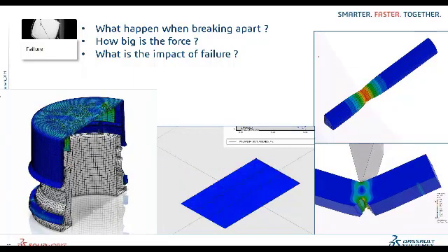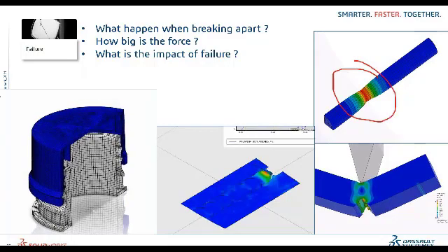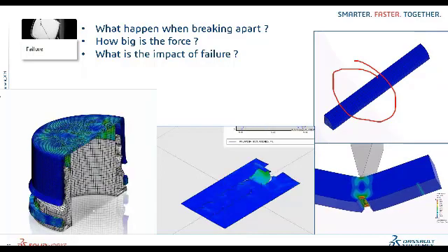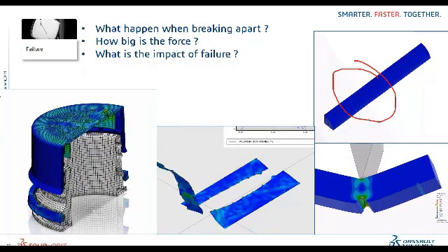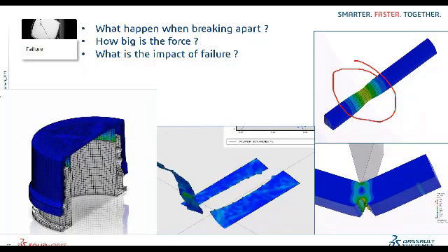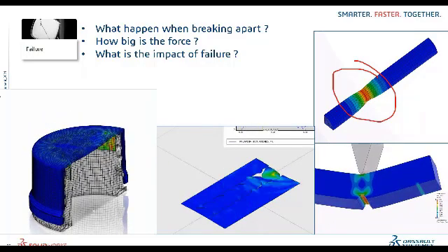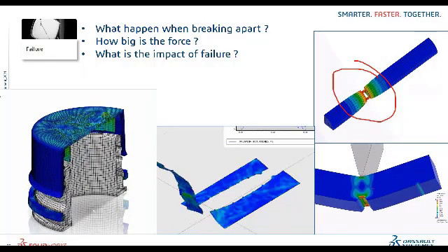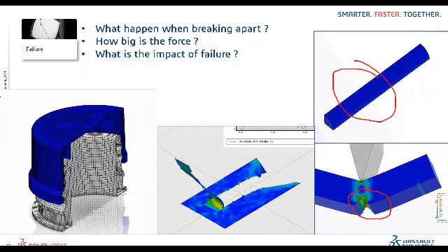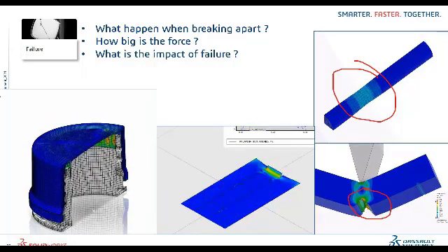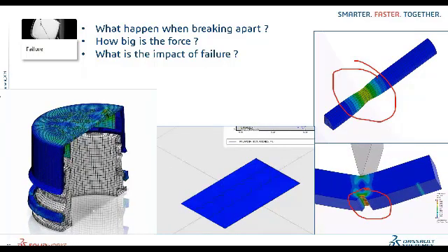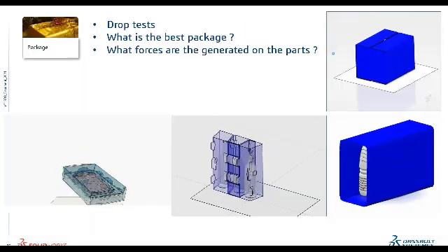This is the case where we perform a test in the universal testing machine in order to understand the tensile strength of the material. Instead of wasting a specimen, you can just model and apply the same boundary conditions onto the solver, and then you can obtain exactly what you are expecting, that particular stress versus strain curve, from the solver itself. And here we can see, if there is any damage and the load still proceeds onto the component, how exactly the propagation of the failure is going to take place.